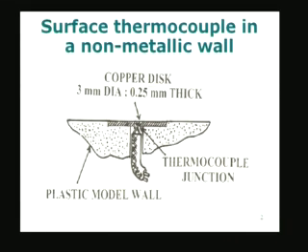So, we have a heat collecting pad. I indicated the copper disc in this case, a thin copper disc to which the thermocouple junction is attached. So, the conduction due to the thermocouple which is attached to the back is modeled according to the equation I just now indicated on the board, which is proportional to the temperature of the junction minus the temperature of the ambient here multiplied by that factor.